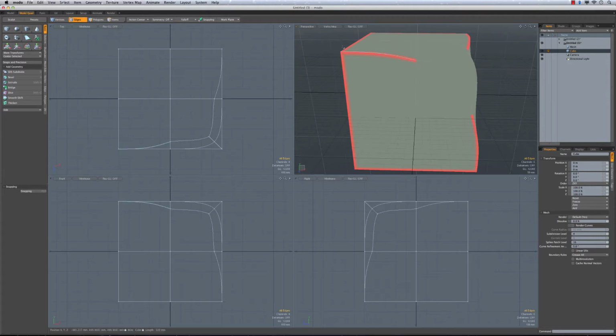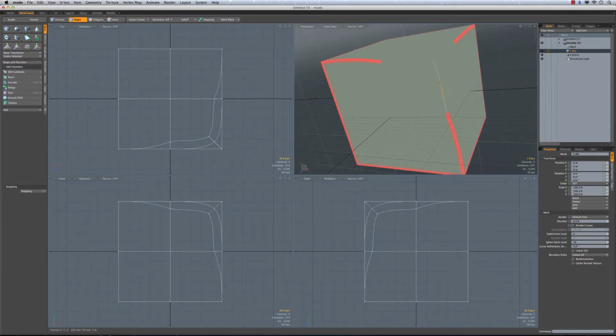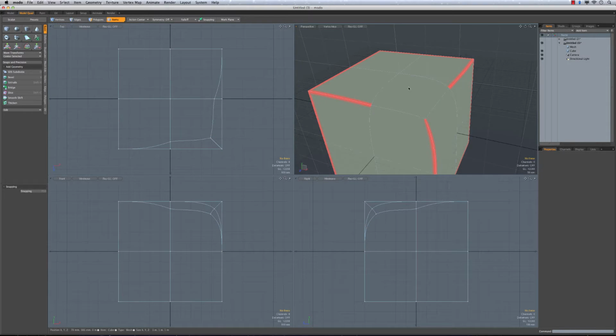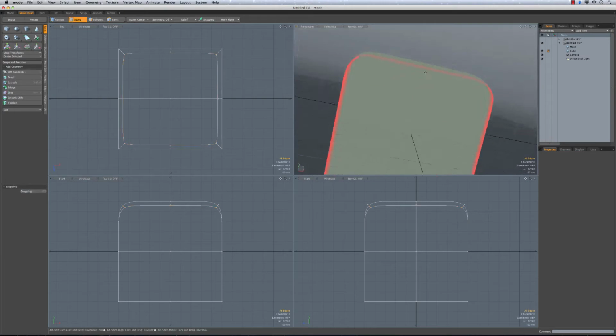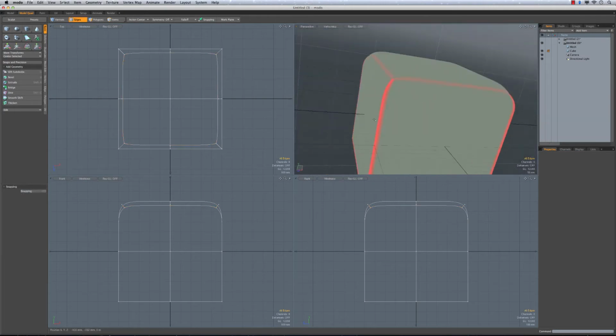And typically, the idea is going to be to keep entire loops together, and that will allow you to get something that actually works. So if I were to take this one here, and let's go ahead and fully weight that again. I'm going to pull that up to 40. And then I'm going to grab the whole top section here and just get the boundary. And on this part, I'm going to pull my weight down to something like 10%.